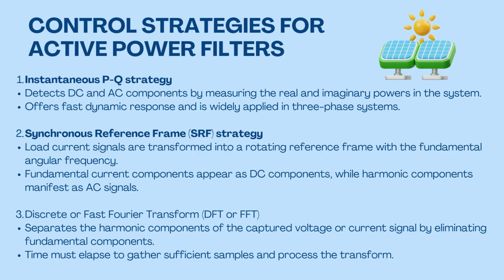The second one is the synchronous reference frame (SRF) strategy, in which the load current signals are transformed into a rotating reference frame with the fundamental angular frequency. In this strategy, the fundamental current components appear as DC components, while the harmonic components manifest as AC signals.